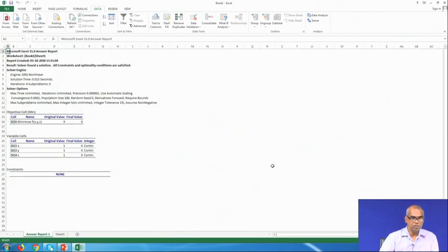Click on the answer report, you get more information about the solution procedure, how much time it took, 4 iterations were required, original function value was 9 and original initial guess was x equal to 1, y equal to 1, z equal to 1, and finally we converge to true solution x equal to 0, y equal to 0 and z equal to 0. Corresponding minimum function value is also 0. So, this is how you can solve a multivariable unconstrained optimization problem using Excel solver.